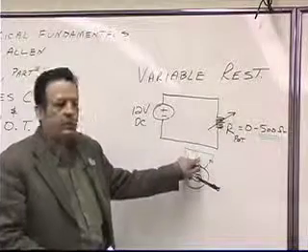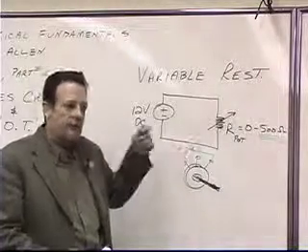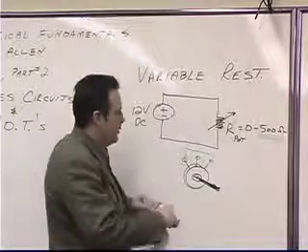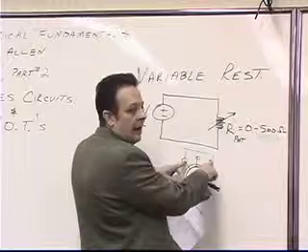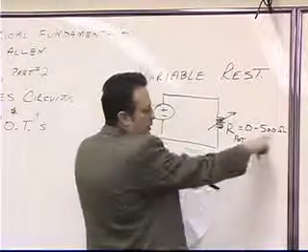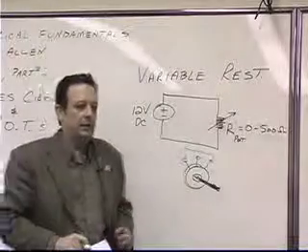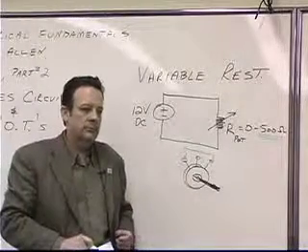So that's something that you have to experiment with by connecting an ohm meter to the 2 leads that you're going to use, and then twisting the knob so that you know is it going up or down. What I'm saying is, if you connect an ohm meter between the 2 outermost leads, you're going to get the maximum opposition to current flow that the potentiometer is rated at.